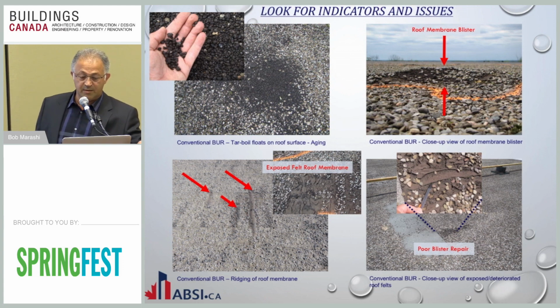Here, I just put an example of a poorly repaired blister. Somebody put a modified cap sheet on it without removing the old stuff and left the corner open. Now you have felt membrane exposed, and you're still going to get a hole in a few years. So that was not a good patch.